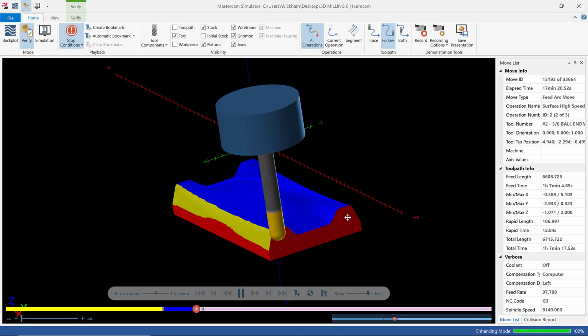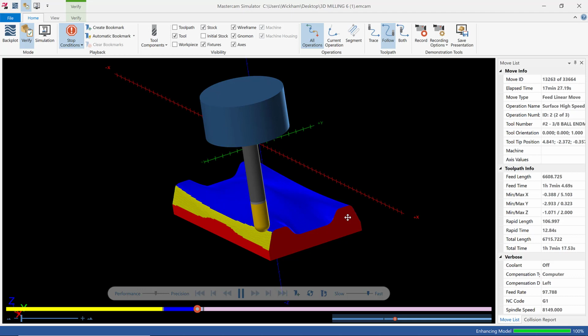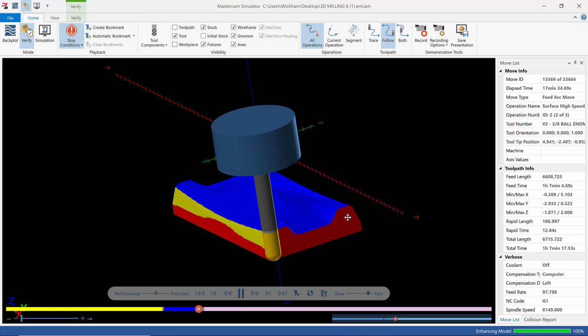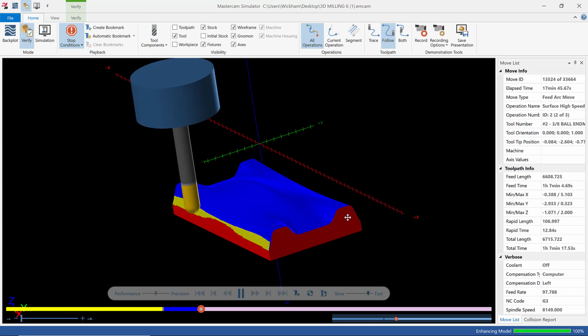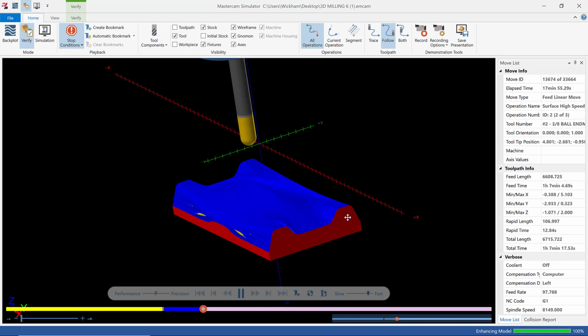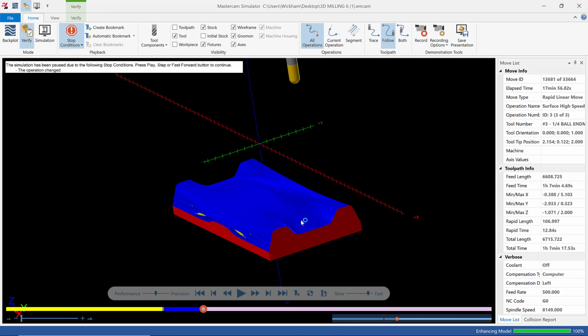Alright, so almost done with the semi-finish. And again, this should be leaving 3/1000ths of material that the finish cutter will finish up. So we should have a 3/1000 amount of material left and a 1/1000 step over to clean up. So that's pretty good. Alright, so there we are there. We'll let this load. And again, this is the one that takes all the time, is the finishing. So let it finish up. And we'll finish it.